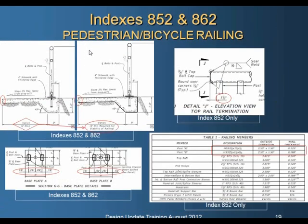Taking a look at Index 852 and 862. Up at the top left, these are sections from the drawing showing the 3-foot minimum dimension of the cross section. We had some questions. Some people thought we were specifying that the sidewalk had a minimum of 3 feet, which is not the case. Our intent was that we required the 3 feet for stability of the railing. Therefore, we clarified that note there.